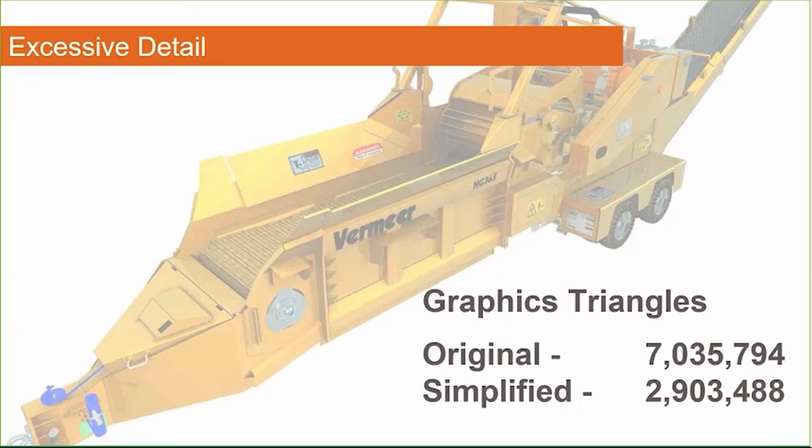So he goes through in more detail some extra tools that you could start using to simplify the geometry, but this is the biggest thing that you can control in a large assembly. When you start getting into something of this magnitude and you want it to perform nicely, you really need to start exploring some techniques to simplify highly detailed models down at the big, large assembly level. And that's the beauty of SOLIDWORKS and taking advantage of configurations. So definitely look into doing that. And the assembly visualization tool is the greatest tool to start pinpointing where some of the troublesome parts could be.